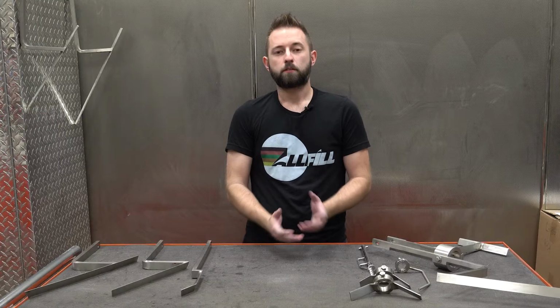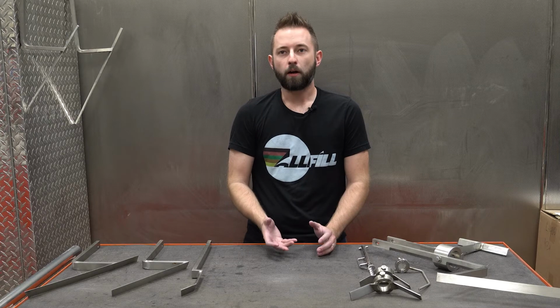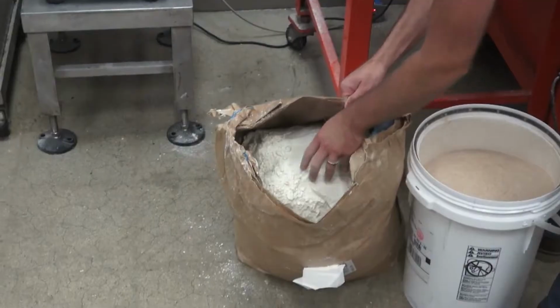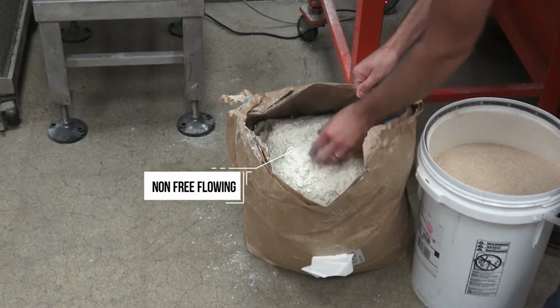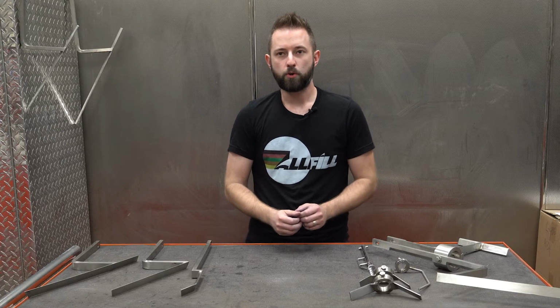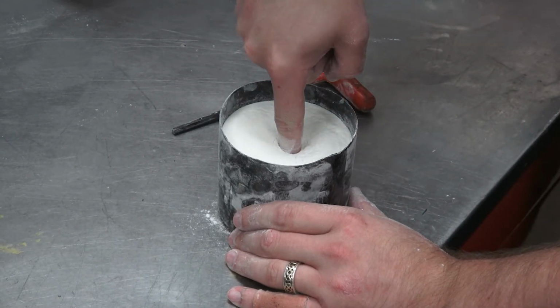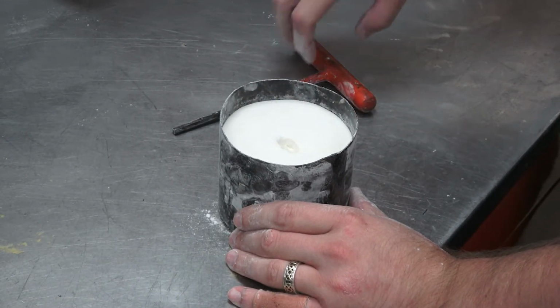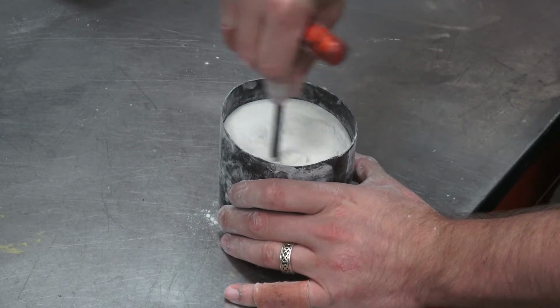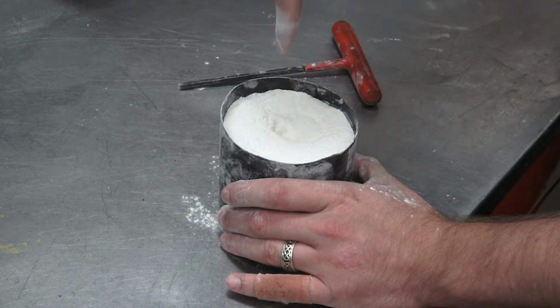Some products, continuous agitation is absolutely a requirement. It's typically for a product that is either very non-free flow and needs additional continuous agitation to keep it moving down to the auger. Or you have a product that is what we call a tweener, where it has free-flowing characteristics but also non-free-flowing characteristics. Or in particular, a tweener that will actually change states depending upon if it's moved or not.